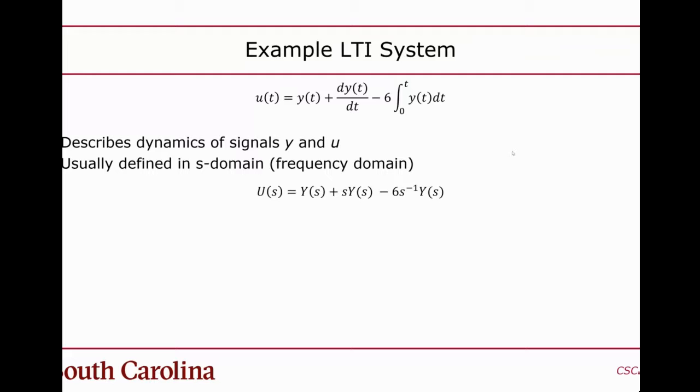And when you have an integral, you multiply by 1 over S, or S to the negative first power. And then the constant scalars just remain in there, and it becomes a function of S instead of t. Notationally, you also capitalize the names of the functions. Notice that at the top I have lowercase u and lowercase y, and then I made them uppercase U, uppercase Y. That's just a convention that people generally follow. And then instead of t, it's of s.